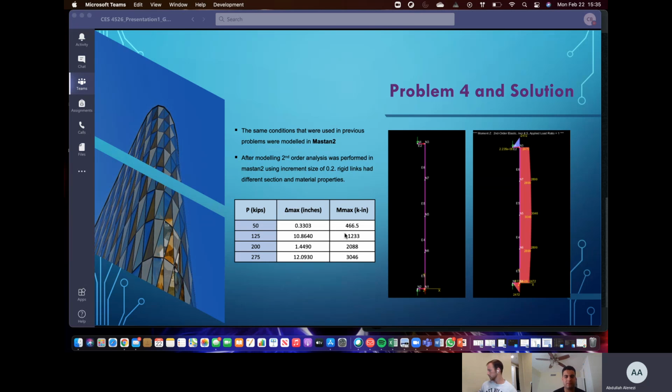The materials are defined first by using properties, define material. After inputting the necessary material details, Young's modulus, Poisson ratio, and after defining materials, the materials are attached to the section by selecting the element and pressing apply. The eccentric link was modeled with a different section and material. Fifth, define end restraint and load.